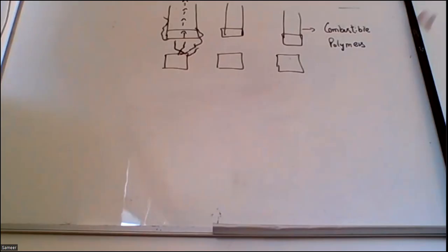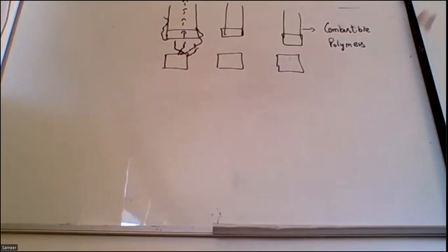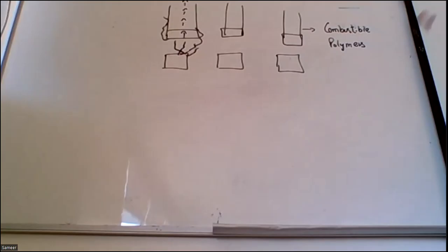Sometimes, as I said, the extinguishing mechanism is installed there, but it may not be effective. Why? Because in a process industry there are various types of obstructions available, so your agent may not be directly interacting with the material itself. There is always a risk, and there is always a holding time of the gas, like 5 minutes, 7 minutes, but during that time the flame can propagate. So to buy more time, we direct the flame towards the more combustible material.